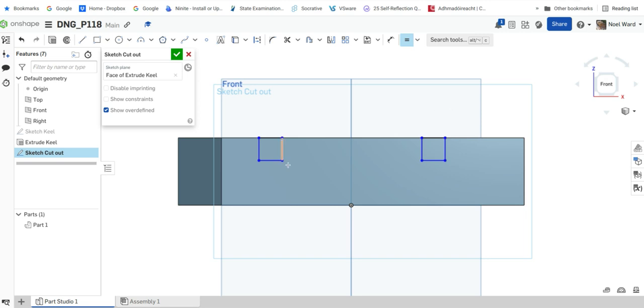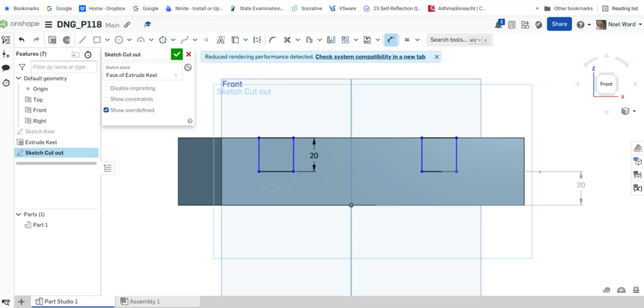So they've moved to equal size, and what I need to do now is I want to put in a dimension for this, which is 20. And everything's 20 now. It's 20 down, 20 out, because of the equal relation. If I go there, it'll put it in grey because it's already there. It's already got it. So now I want this a distance of 20 up. It's already got it too again, because that's 20, half of the thing.